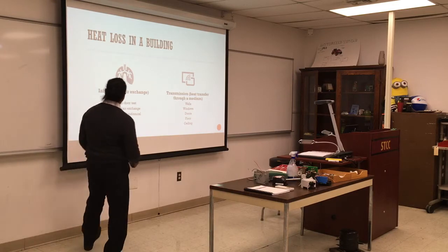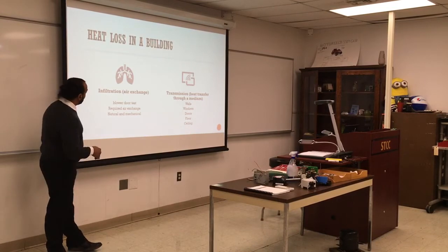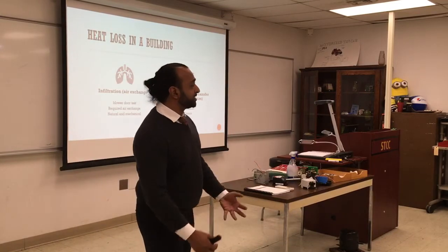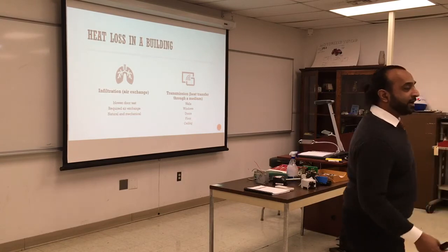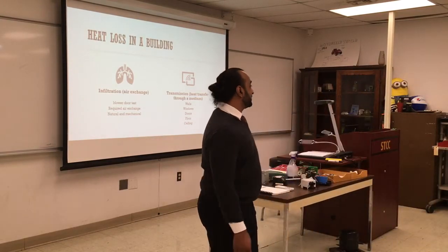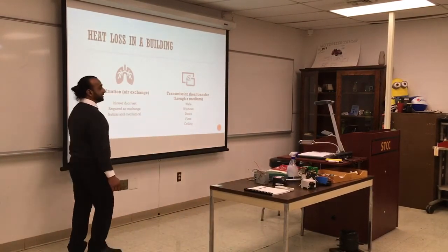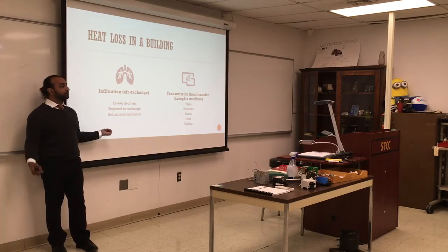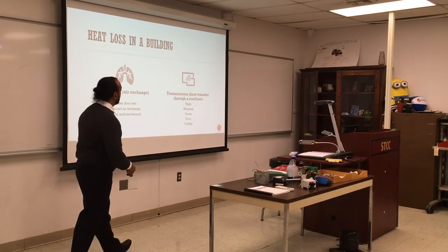Okay. Infiltration is air exchange. This is how the house breathes. We want that. And we talked about that last semester. How much porosity do we need? How many holes do we need? And we said that it's better for us to have control over the air we bring in. But this became very, very important, and a lot of companies had to go and retrofit their air exchange because of COVID, right? You have to change the air. If we have the right amount of exchange, probably we have more dilution of particles.